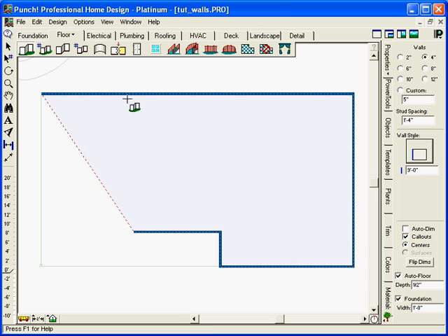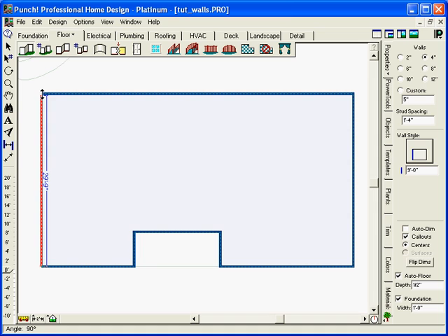The shaded area that you're seeing displays the possible enclosure if you were to draw a wall from the last point to the first point. The dotted line shows you exactly where that wall would go. To finish, set the direction of the cursor, hold the Control key down to lock the direction and also to auto-close the shape as you release the cursor over the first point.